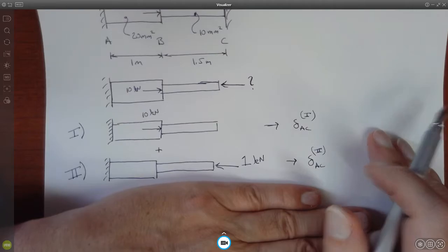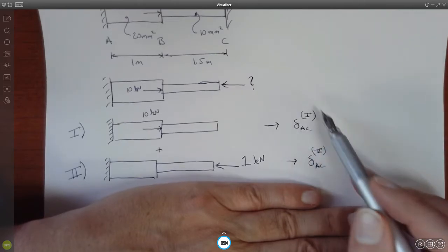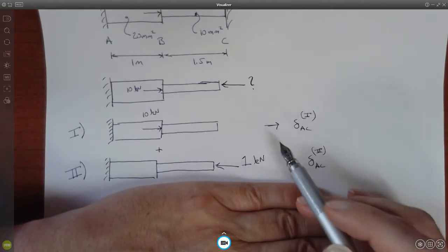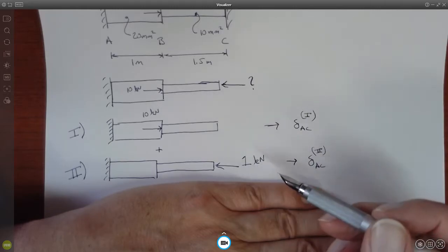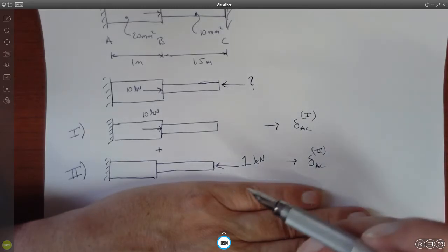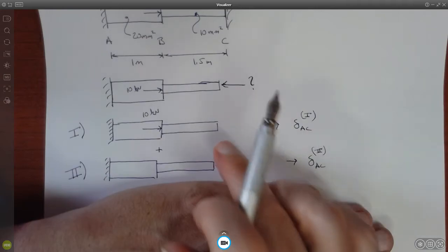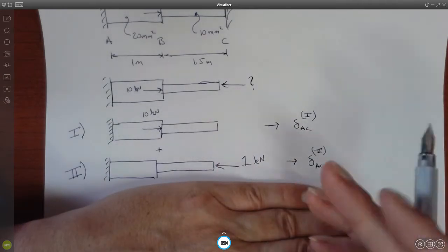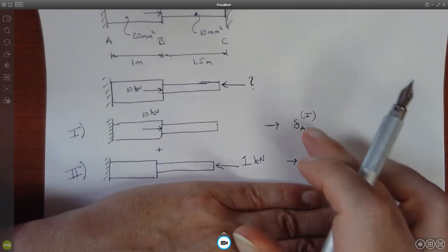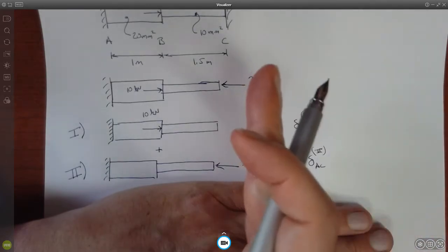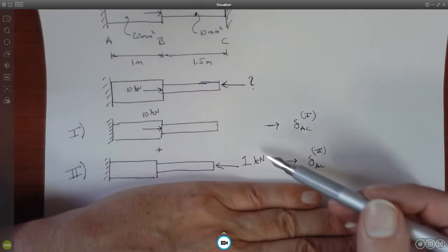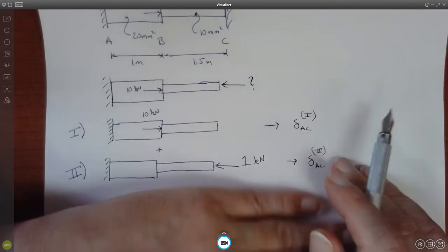And then from that, we figure out the elongation, as if there was no force here. Then we figure out the problem with just the force, how much that would push it back, basically correct this. And then we scale it so that this would equal the negative of this. So basically enough so it pushes it back. Then we superimpose the two together, and that'll give us the total solution, okay?